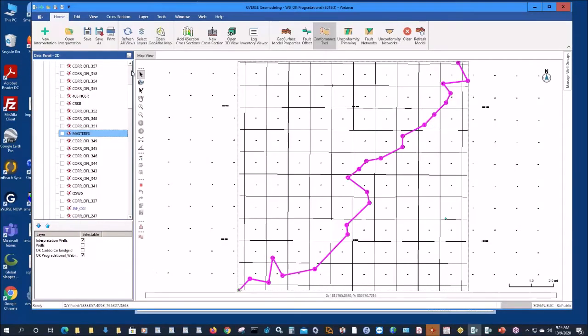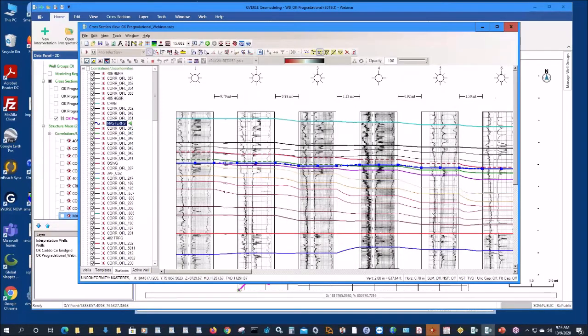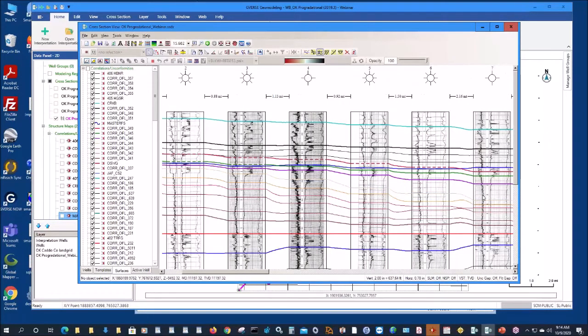And again, the little trick is to double click on your cross section and bring it back up. So you'll notice that the surfaces are not quite so rogue, the red and the green here. They're more or less conforming to the purple surface. However, I do want to use another modeling tool here because they're jumping up through that flooding surface. You notice the dashed lines, meaning they're not picked as hard points, but they are showing up because I do have surface projection on.